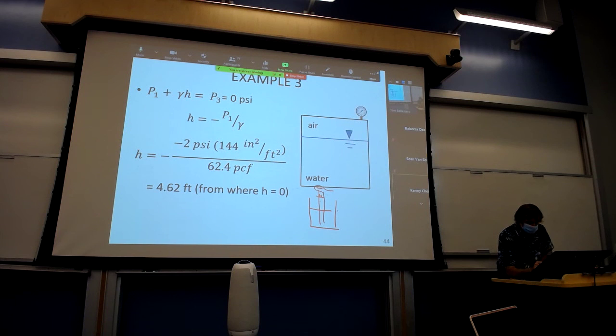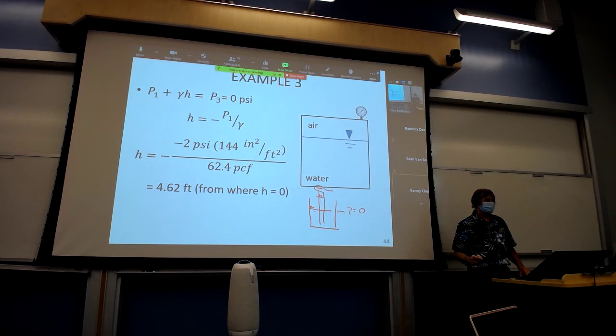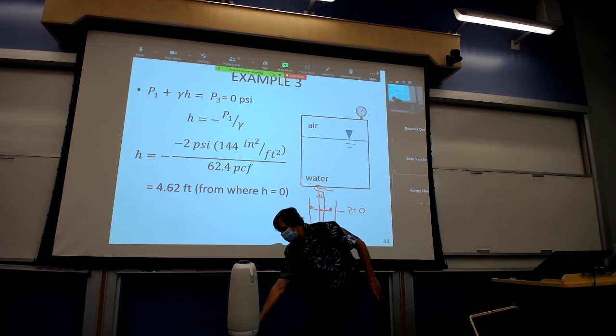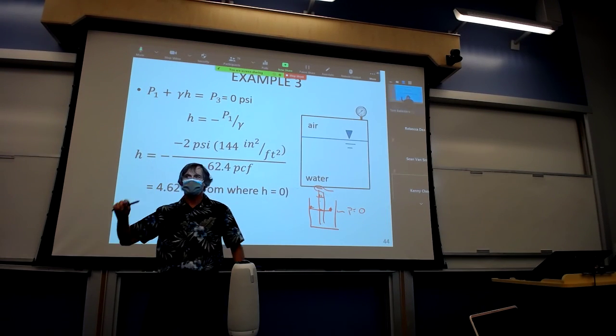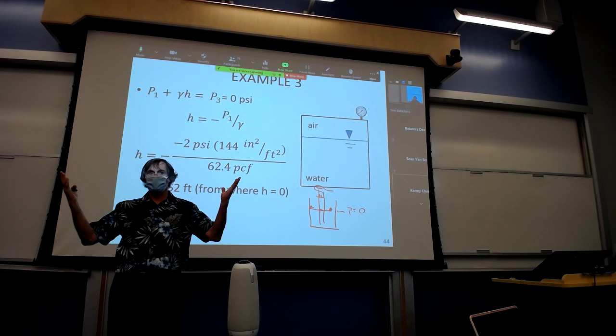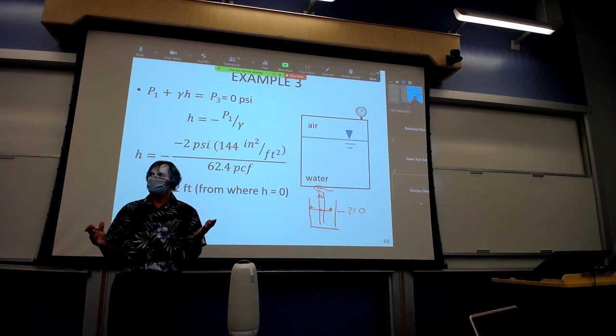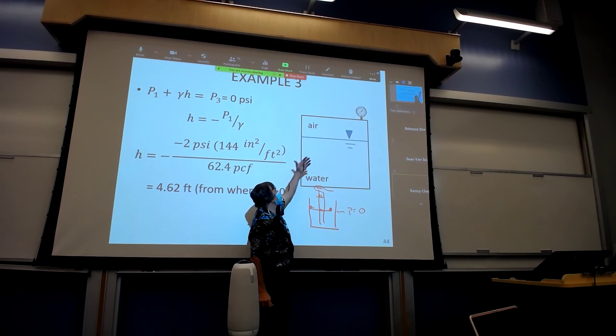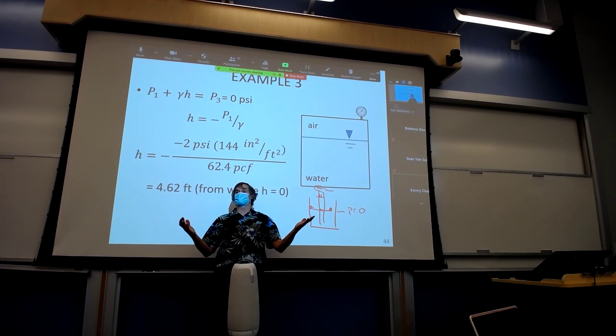And so if this is 0 along the free surface outside here, dP dx is 0. If I move from this location to this location, I'm going horizontally, even though physically to stay in the continuum, I went down and up into the straw, but I went through a continuum. The pressure, dP dx, has to be the same. There's no change in pressure if you move in the x. Okay? So this would be the exact analysis of what's happening in the tank. And you've seen this before, I know it. You just never applied math to it.